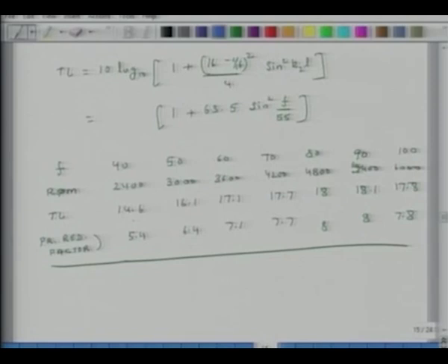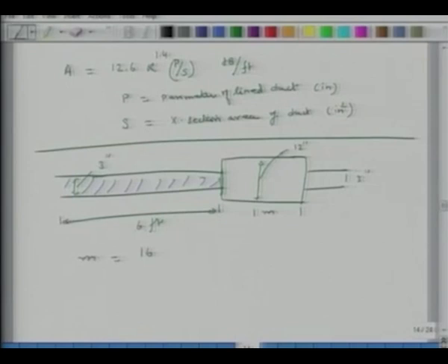So in that case, A equals 12.6 times, and I assumed alpha of 0.08, which is fairly high, times pi d, the perimeter, over pi d square over 4, my area. So if I do the math, what I get is 0.49 dB per feet.